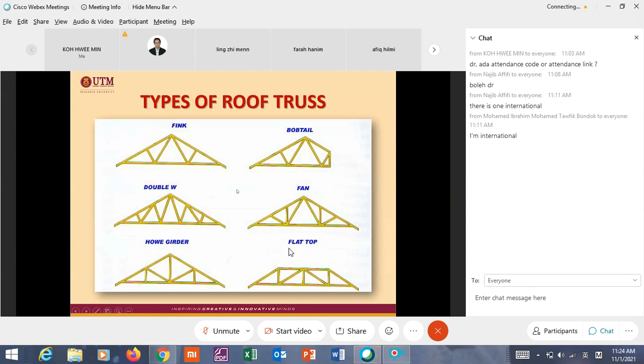The difference here is for what we call a Vierendeel truss. Here the member is subjected not only to axial force but also bending moment and shear force. So this is called a frame, but some definitions consider it also a truss, and we call it Vierendeel: axial force, shear force, and bending moment. So it is not included in the scope of our lecture.